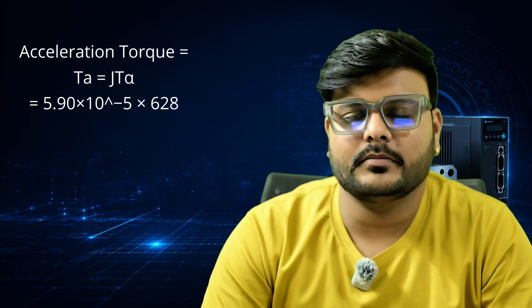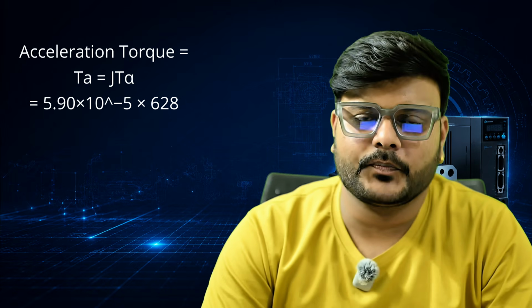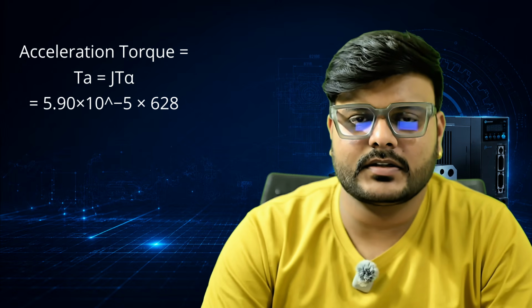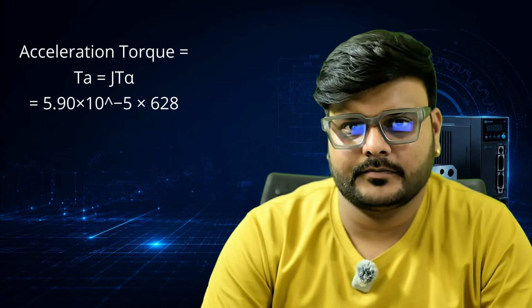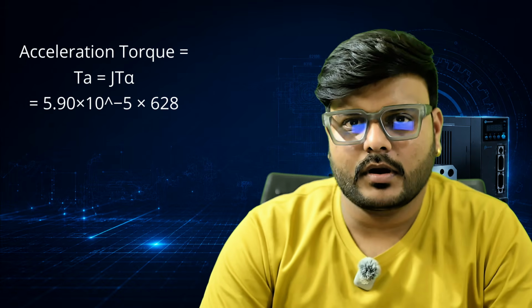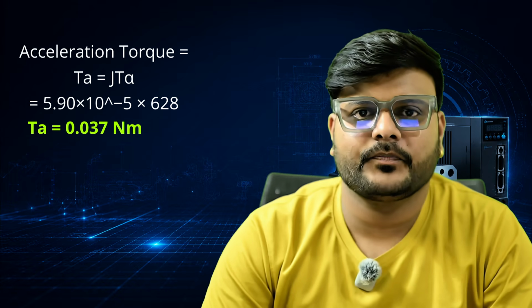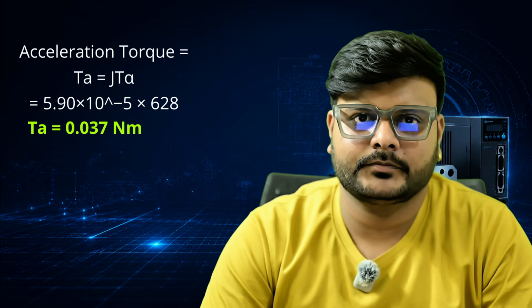Substitute the values in the formula. We know our total inertia is 5.90 multiplied by 10 raised to minus 5, and our angular acceleration is 628. So our total acceleration torque is 0.037 Newton meter.